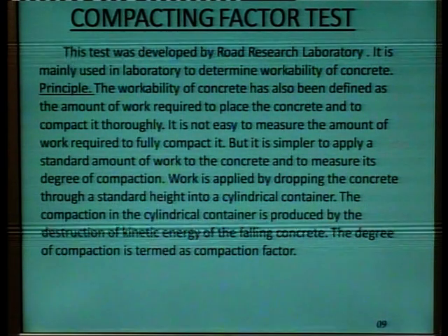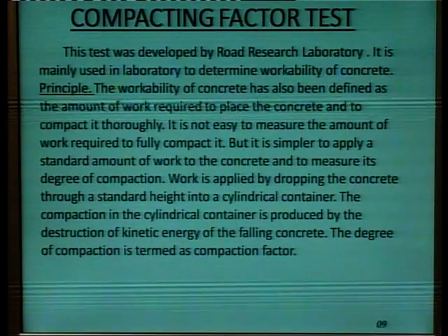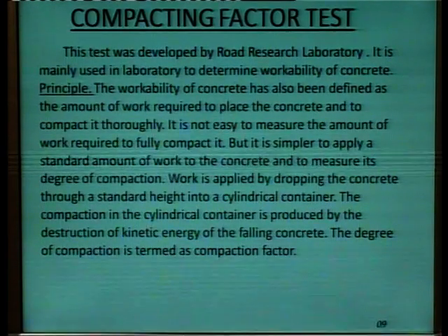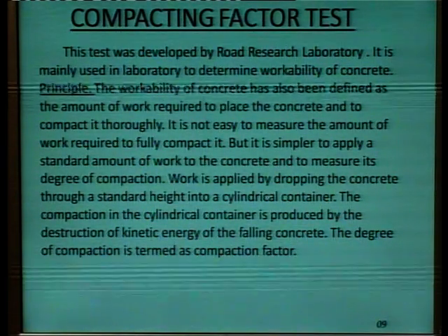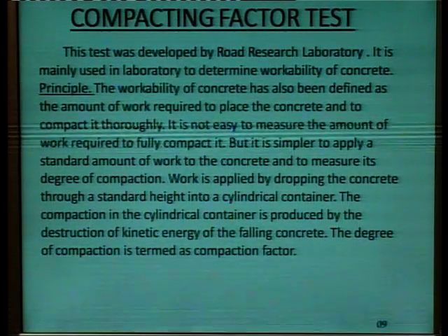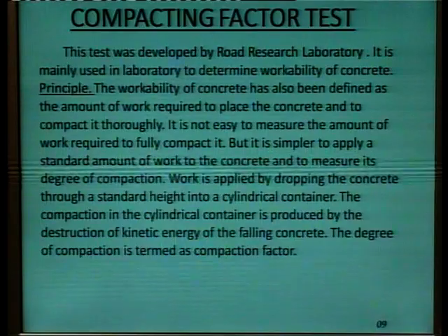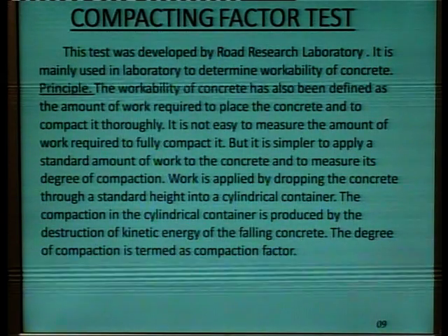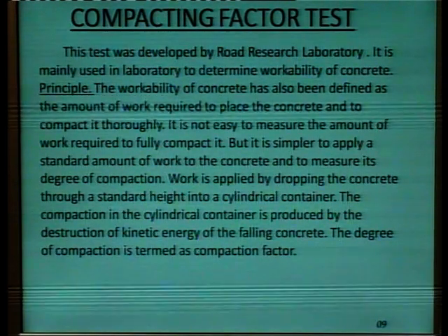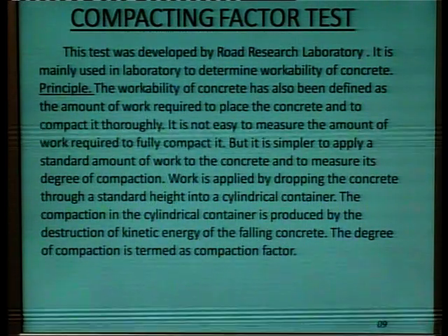Principle of this test: the workability of concrete has also been defined as the amount of work required to place the concrete and to compact it thoroughly. It is not easy to measure the amount of work required to fully compact it, but it is simpler to apply a standard amount of work to the concrete and to measure its degree of compaction.